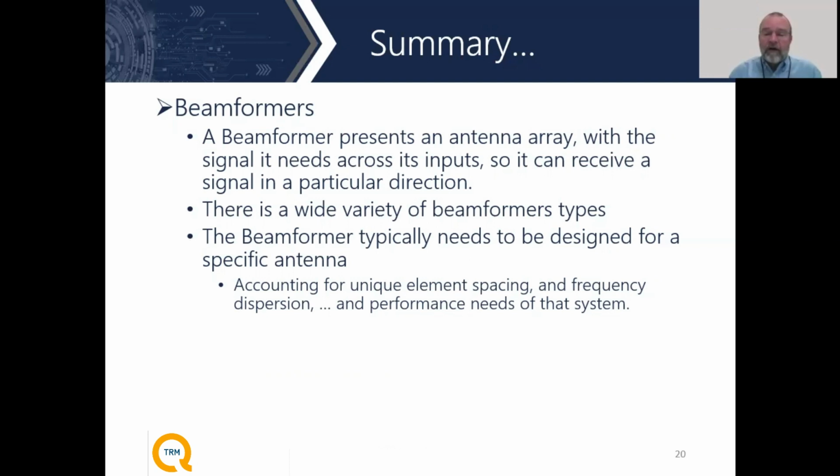The other thing to keep in mind is that the beamformer needs to be designed in concert with the antenna aperture design. There are lots of variables that you get into when you start designing antenna apertures and phased arrays, and all those variables need to be taken into account when designing the beamformer as well, because they work together as a system. If you change one thing on the antenna array, the beamformer will behave differently when hooked to it in the system. Therefore, all those variables need to be looked at.